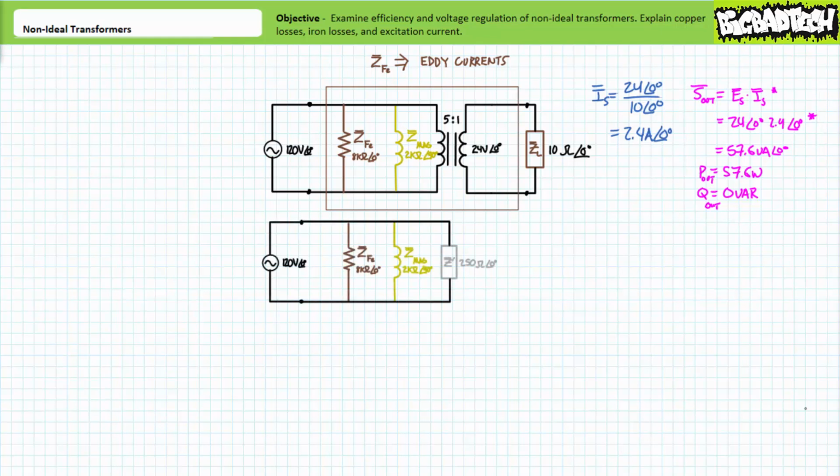As previously, let's now analyze the primary input side of the transformer using the reflected impedance seen by the primary winding. Given we've included yet another leakage path in parallel with the reflected impedance, we might expect this model's behavior to increasingly diverge from our ideal expectations. This additional current path in parallel will undoubtedly draw more current from the source, only this time, the additional current path is resistive in nature and can be expected to consume an amount of real power considered a loss. Let's see if this is the case.